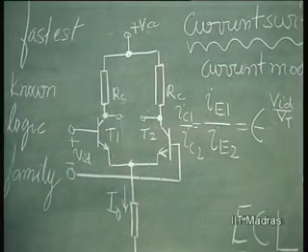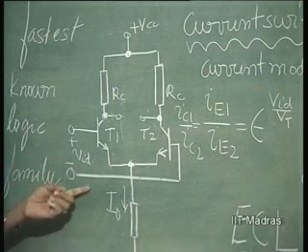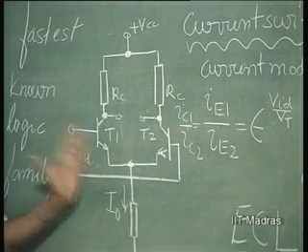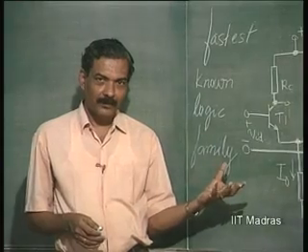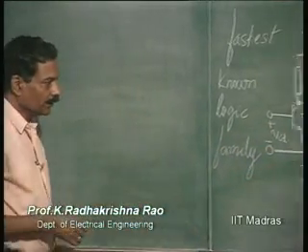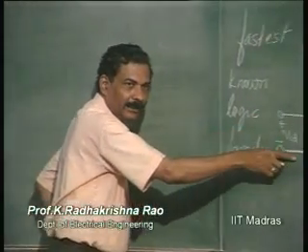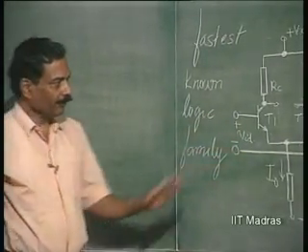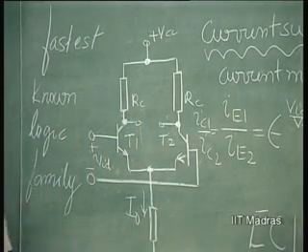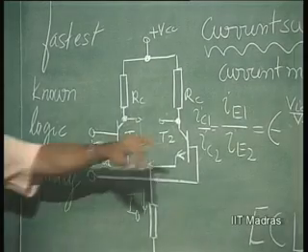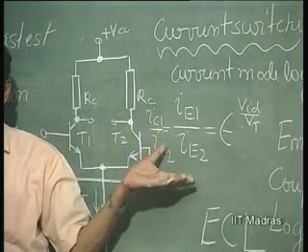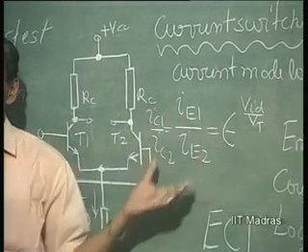Let us investigate this. How much voltage is needed at the input in order to switch the current totally from one transistor to other? This is an important aspect of finding out the drive requirement for such logic families. So, the question is, what is the VID required to take the current from one transistor to the other and vice versa? Now, if you see the relationship, it is exponential. That means, when VID is plus infinity, and VID is equal to minus infinity, only this takes place.